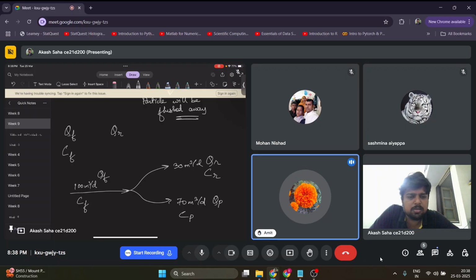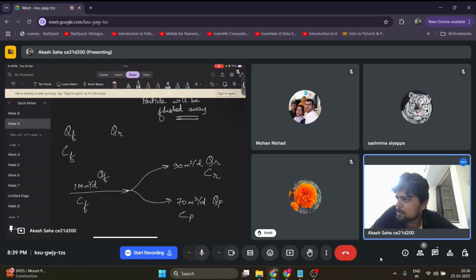Yes sir, suppose I have a sample whose BOD is already very low and it has no organic waste either. To what limit can it be treated, or will it not be treated at all? You see, the type of treatment you are providing depends on the BOD by COD ratio. If the biodegradable organic matter present is too low, then we will go for some other kind of methods, treatments, some chemical or physicochemical techniques. You're asking that only, right?